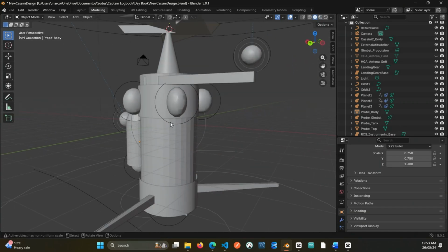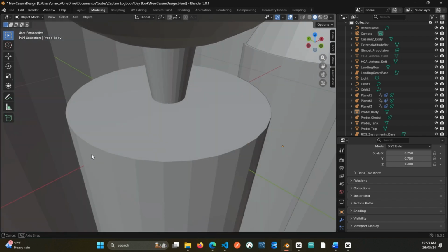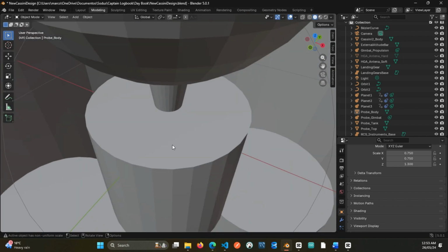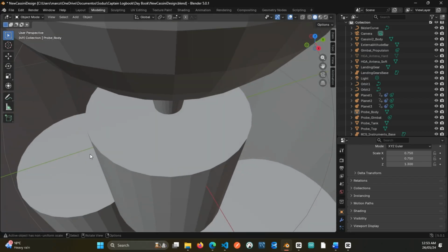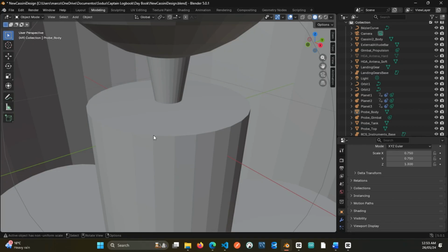And I also want to use calculus. This is the internal point. To calculate the volume of propellant and what is the mass of each one of them, put it in a table, sum everything, and we're going to have a representative form of mass very close to the reality.